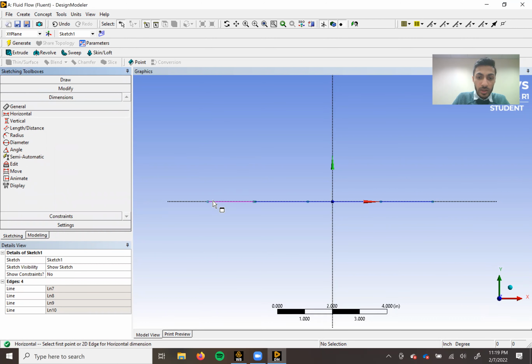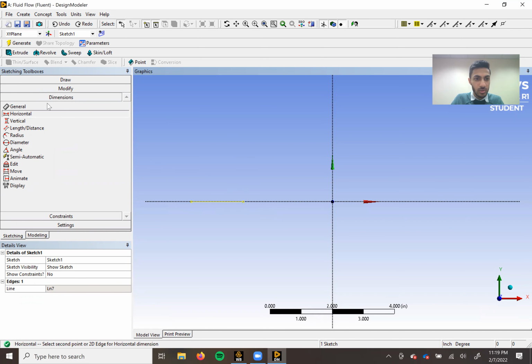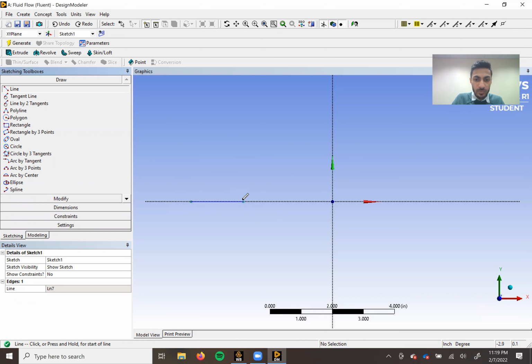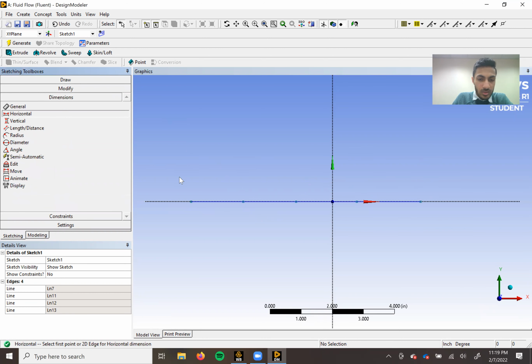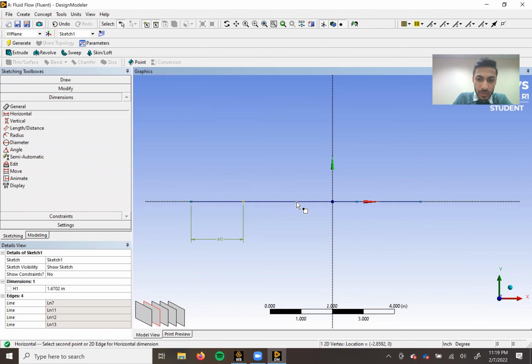We're also going to go ahead and dimension these. I'm seeing right here how these two lines aren't connected. You can tell because there are multiple endpoints there. So I'm going to go back and make those lines again, making sure that they're end to end and sharing endpoints. Something you're going to want to make sure you're doing throughout, because all of these lines do need to be connected. I'll place all the dimensions here, and I'm going to fill in the values after I've got them all dimensioned.